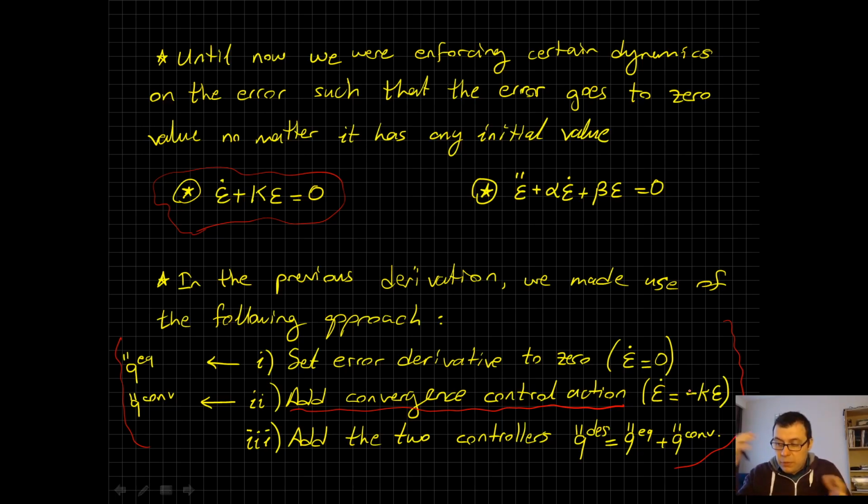I'm sure that most of you have already heard about the sliding mode control theory, but just to give an idea of what's going on over there, I can tell you that you simply change the continuous convergence to discontinuous convergence and analyze the discontinuous boundary conditions, the discontinuous differential equations there, which provides you better convergence of error with some drawbacks like chattering and others. And that new way of deriving will be called the sliding mode control approach.